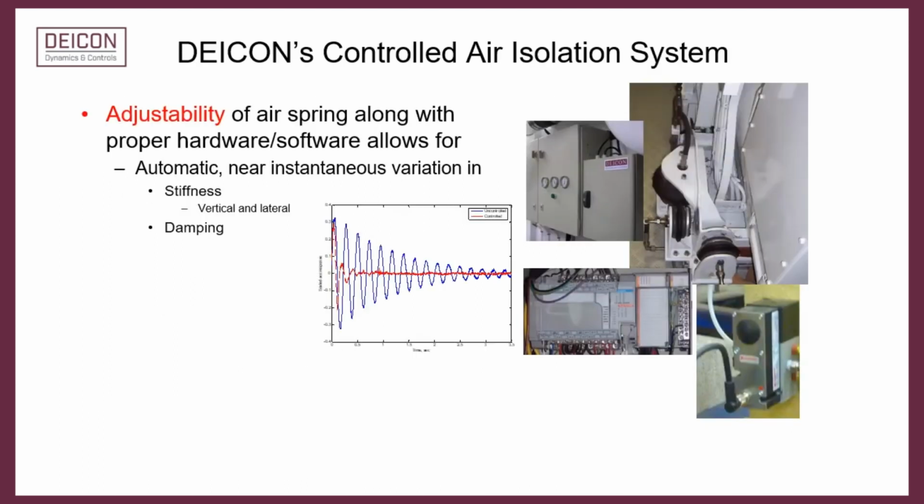As mentioned earlier, the unique feature distinguishing air springs from other isolators is their adjustability. This feature of air springs, i.e. adjustability, in conjunction with proper software, allows for on-demand change in the states of the isolation system in real time, adapting it to the current applicable conditions. All of this is done without adding massive and bulky hardware to the system. As such, there is no weight penalty, which is important in marine and other automotive applications.